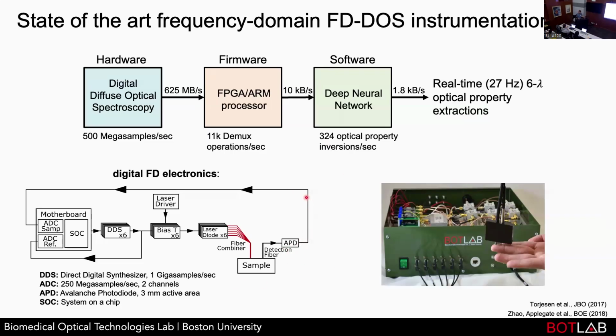We send the signal from the avalanche photodiode into a very fast analog to digital converter. We've played with different acquisition speeds. We kind of settled on 250 megasamples per second. Even when we take measurements that are past the Nyquist band for this analog to digital converter, we call this downsampling.